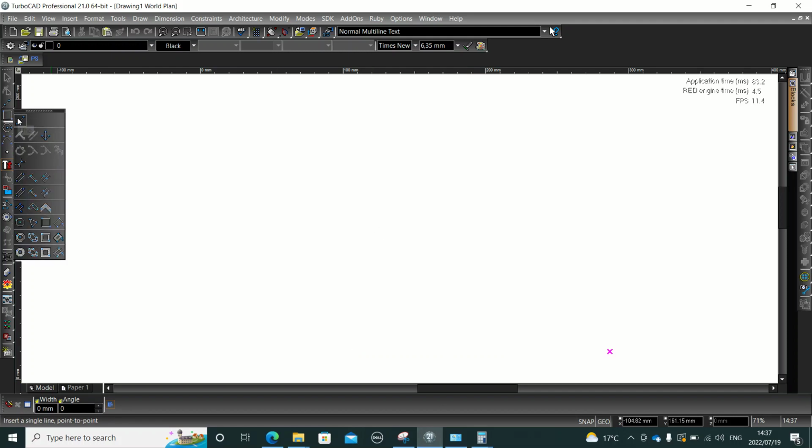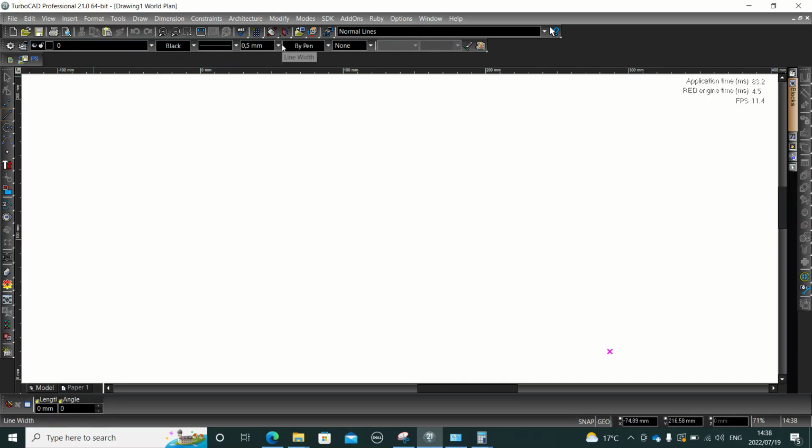To your line tool, and you select the line. Just change the line property to be a center line, and then the thickness, let's leave it as 0.1. Once we are there, we are drawing a horizontal center line first. Okay, you press tab until X is highlighted. Put 0 there for X, and then for Y you can go ahead and put 0 as well, and press enter. Center line will be starting somewhere.